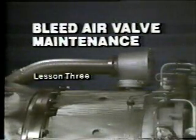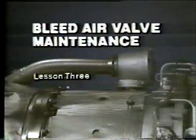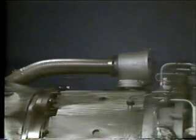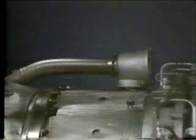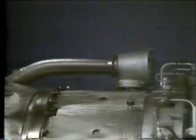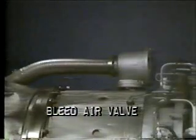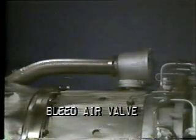Bleed air valve maintenance. Lesson 3. The smooth startup of this engine was aided by the bleed air valve. In an earlier lesson, we described how the bleed air valve functions. During the startup, the valve bleeds air from the compressor to prevent engine surge. At 63% engine speed, the valve begins to close and all of the air is forced through the engine.